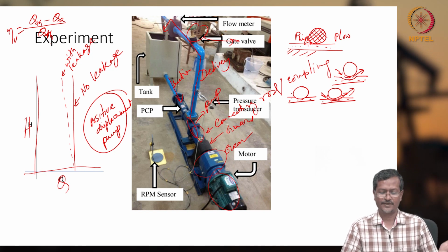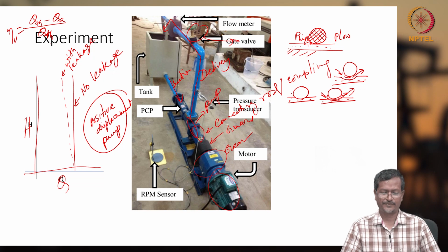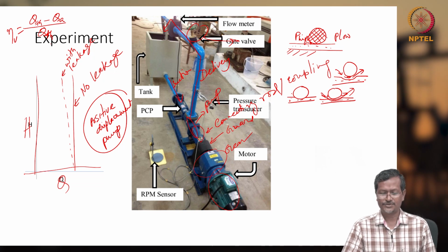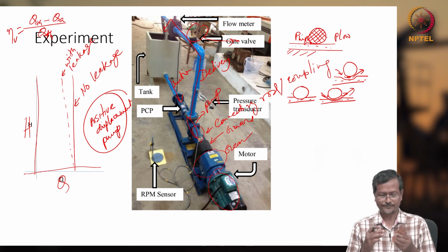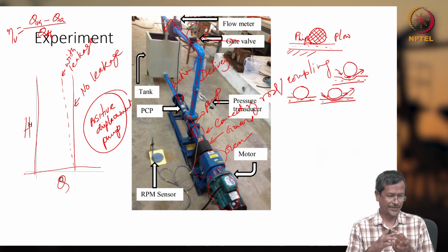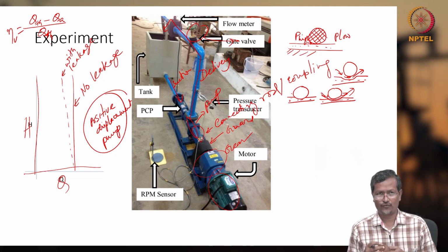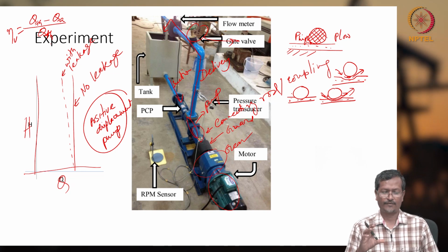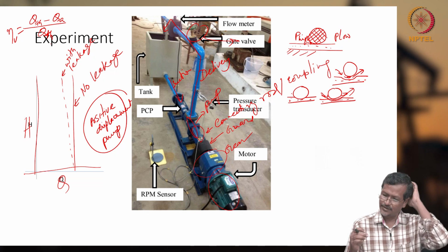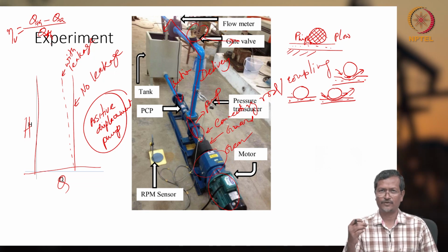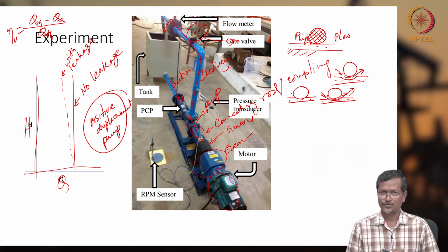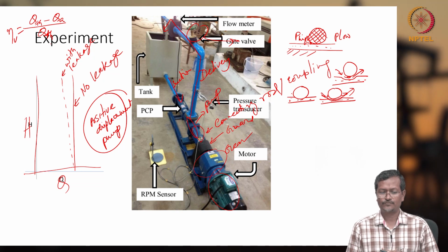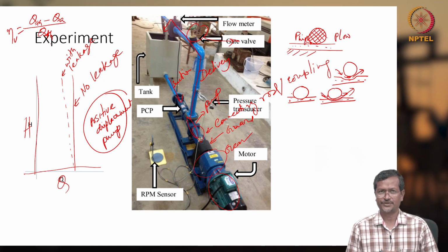Okay. So, 90, 95%, 99% volumetric efficiency is possible, but very low volumetric efficiency may not be possible. Again, normally one pitch of stator is called one stage of PCP. So, how much pressure can one stage PCP give? It will depend on how much clearance you are giving and what type of material you are using for the elastomer, and if you create very high pressure, then leakage will start.